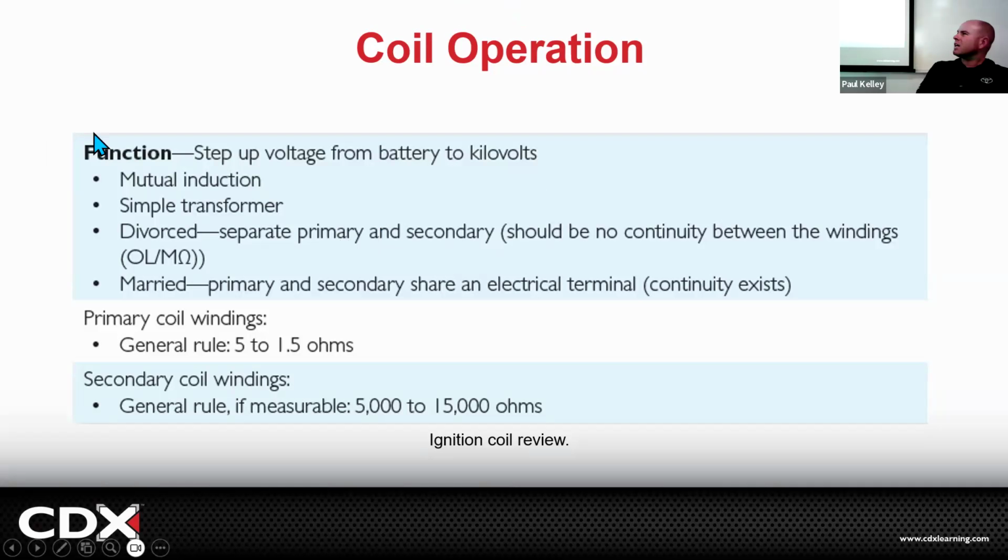Cool. So that's kind of what I'm saying. It goes from the voltage of the battery, which is primary, and it bumps it up to thousands of volts. We typically measure the secondary system in kilovolts, right? So if I say it's a 40 kilovolt system, it's a 40,000 volt secondary ignition. It's 100 kV, 100,000 volts. You're going to feel that one, let me tell you.